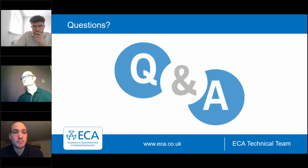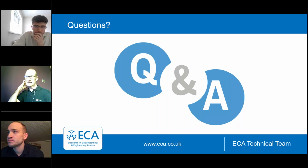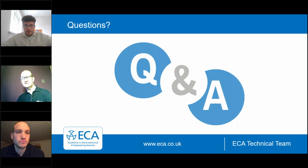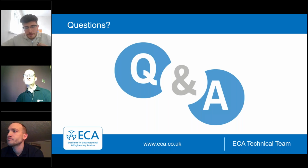Do you want me to go first, Rob, and then you add in what you want? Yeah, it's a 0.63. So in terms of what I've talked about, you would need to check the measurement range of the instrument to make sure that it's accurate at that level. In terms of a calibration certificate, the calibration house will apply a known value and take the measurement from the display. Now, if that measurement complies to the accuracy specification, then they'll still pass it. But whether that's within the measurement range that complies to 61557, you would have to double check with them in order to make sure that that is correct.